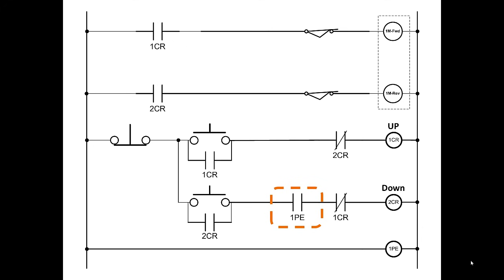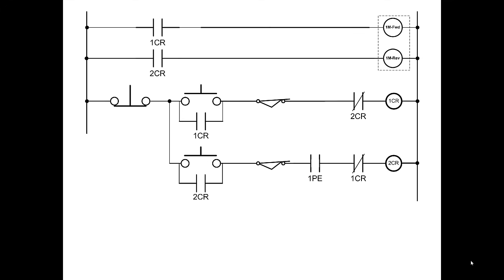So we're going to put the limit switches in a different position. They'll still accomplish stopping the door from moving when they hit the end, but they will also clear or cancel the up-down commands. So there, we've moved the limit switches into a different position. I've also compacted the wiring diagram a little more towards the top of the sheet because we're going to need space for more logic because we're nowhere near done. So the change we just made was we want the limit switches to do more than just interrupt the current to the motor. We need the limit switches to cancel the up-down commands.